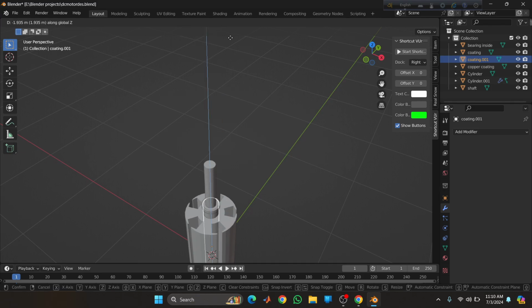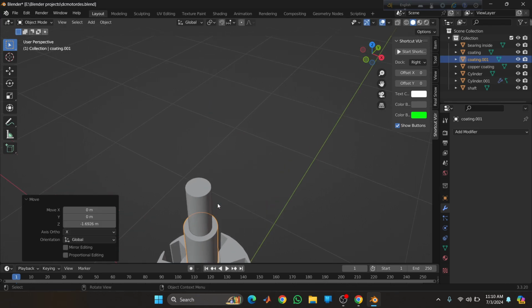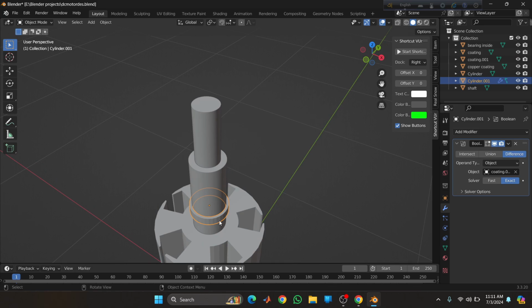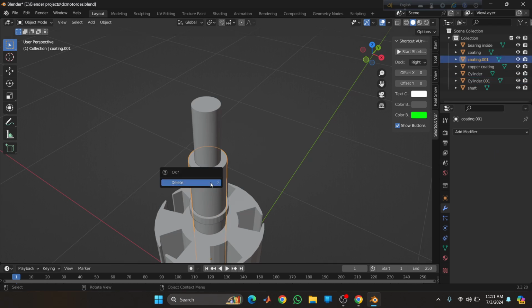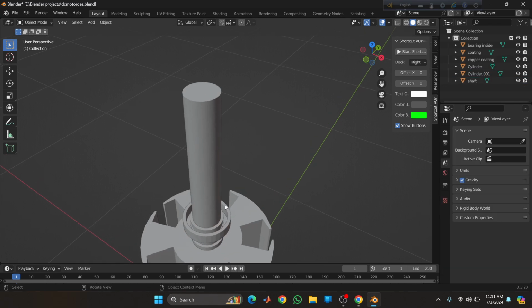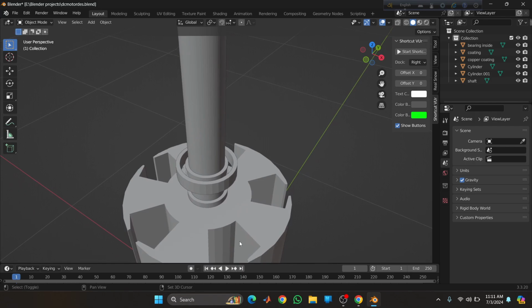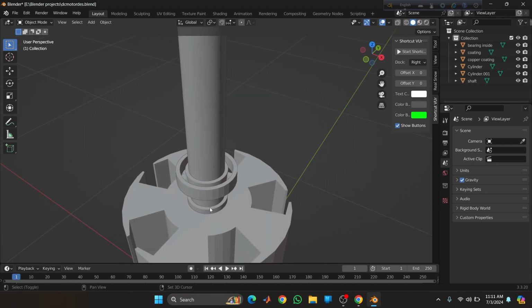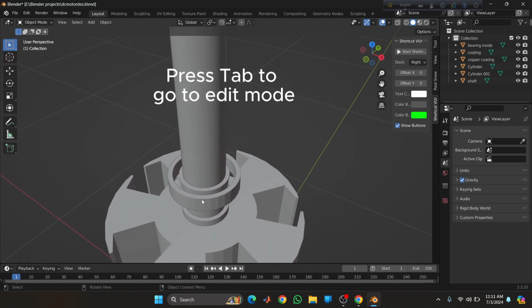Okay, by this thing we'll cut the cylinder. So add the boolean modifier, take the marker and place it on this object. Okay, now apply the modifier and delete it. Okay, so we've got the two rings and now we need to adjust the outer ring a bit.